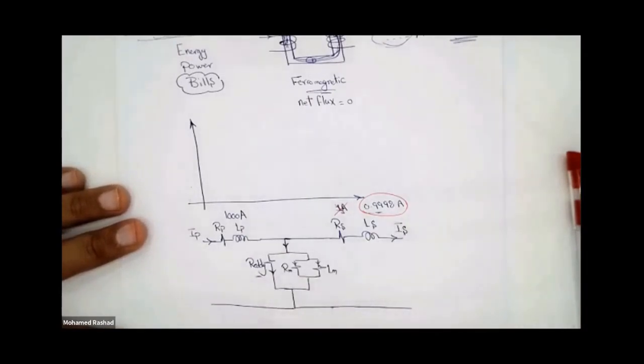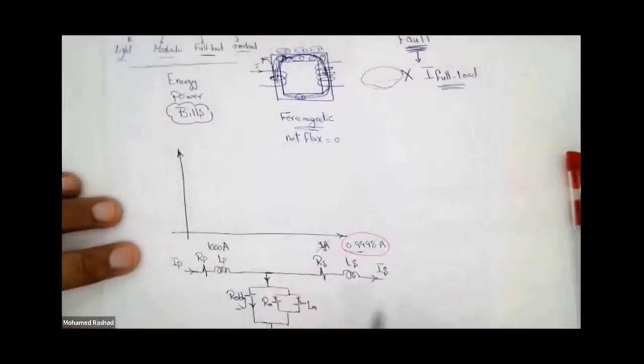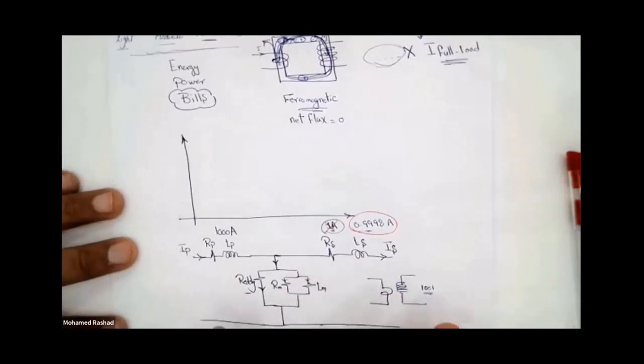One of the manufacturers I was sitting with before also told me that if your current transformer has a ratio of 1000 to 1, in reality, if there's one turn on the other side, it won't be 1000 turns. On the contrary, sometimes they make the number of turns more or less depending on your needs, like making it 1000 and 1 turns, meaning they add an extra turn, so that in the end it results in 1 ampere. Surely they apply a factor to this matter.